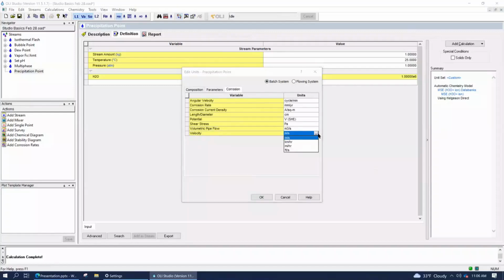Yeah, well, keep in mind, there's velocity and there's flow. There's Q, which is the flow. That's the quantity that gets moved per time step. That's going to be in hours. But when you're talking about things like shear stress, which is what the velocity does, or the volumetric properties with the diameter, these are really just to calculate the shear stress. So they don't actually get involved in knowing what that Q is, the material that's getting transferred. Am I clear on that?